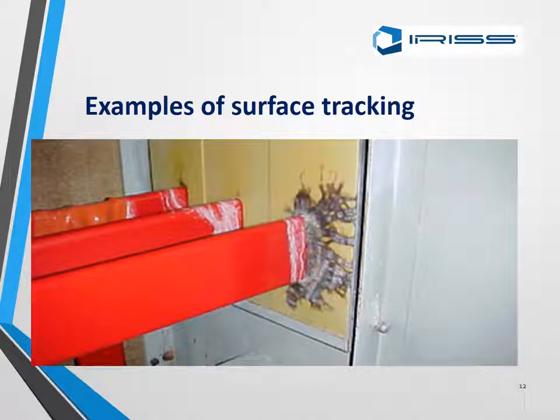Another example of tracking here. As you can see, this is a bit more severe, but as you can still see around the busbars, there is the white residue, and that's the first part of the corona. What's happened is this has been left to go on a little bit, and that's why the tracking has now got worse.